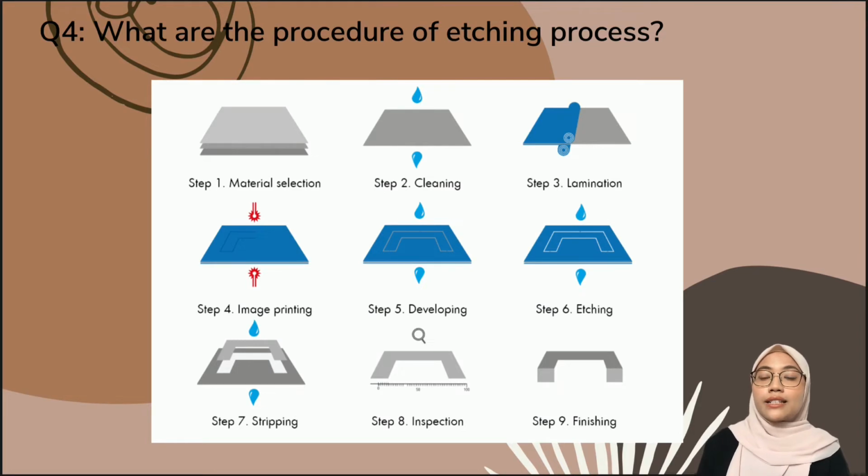Last but not least, chemical etching is very inexpensive, very easy to adapt, and does not wear out unlike presswork tooling. Material thickness and component size are key cost drivers, as you pay by the sheet, not by the part. The more parts per sheet, the lower the price. The thicker the sheet, the longer it takes to etch, and this will reflect in the cost of the components.